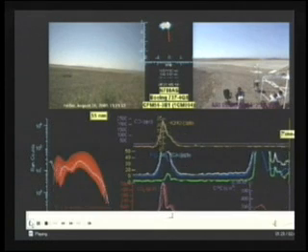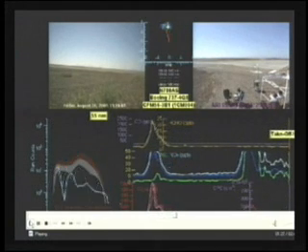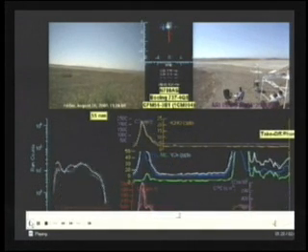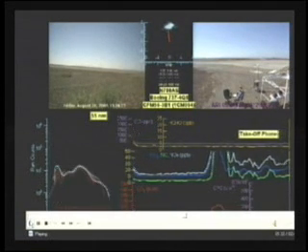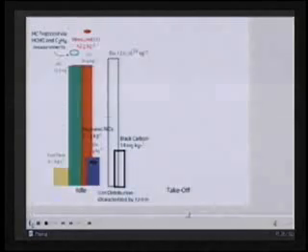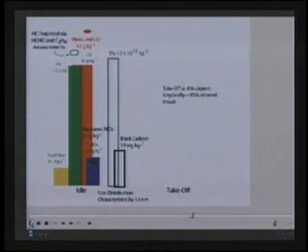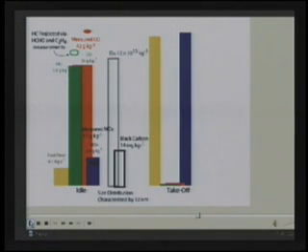That's because we're at takeoff, a higher power. The products of incomplete combustion are almost gone, and the particle size distribution is now peaked at 55 nanometers because there's a lot more soot involved, and we have a larger size distribution that's having a much bigger role in the particle size distribution. The certification values, unburned hydrocarbons and CO, are very low, and now we're comparing to